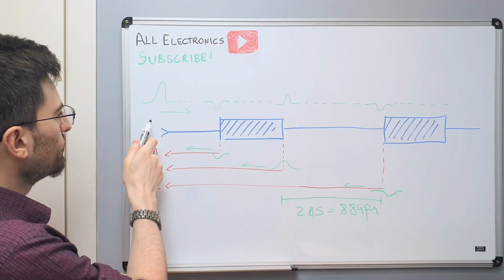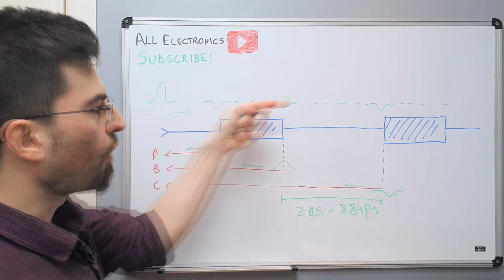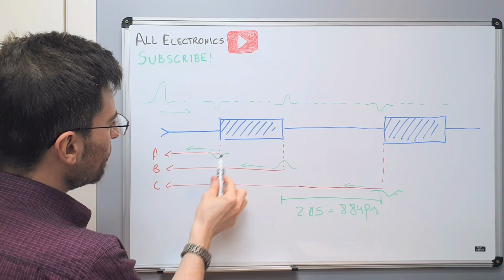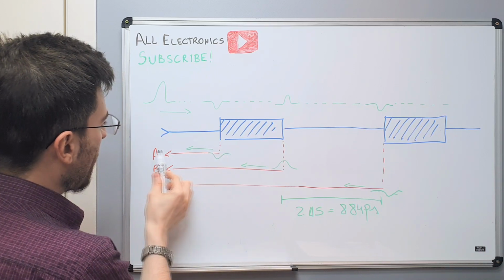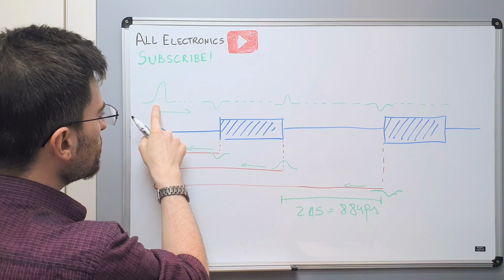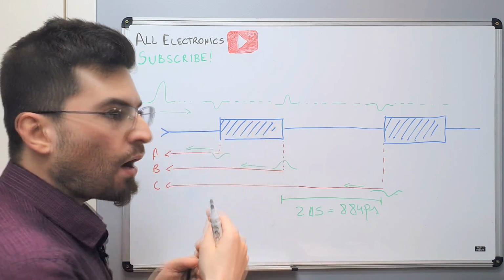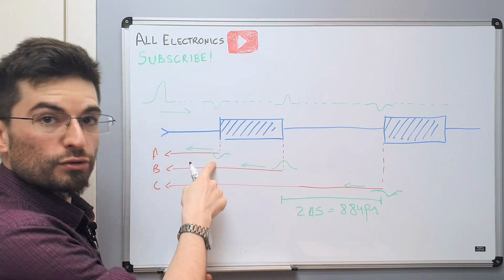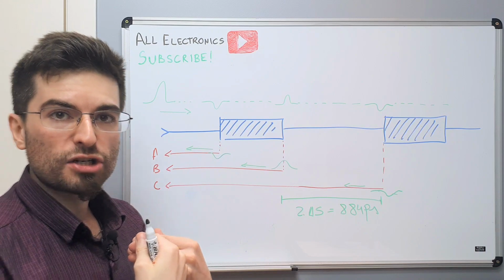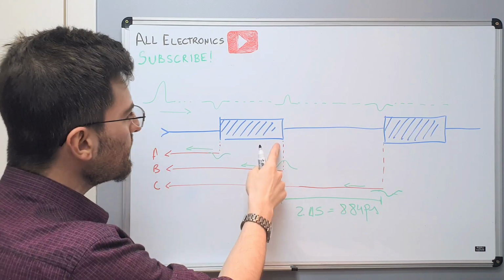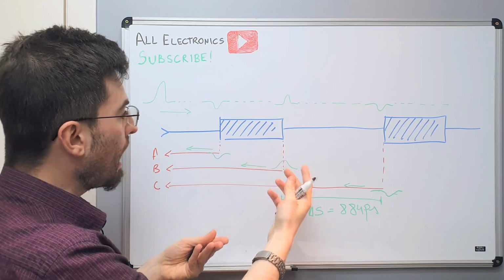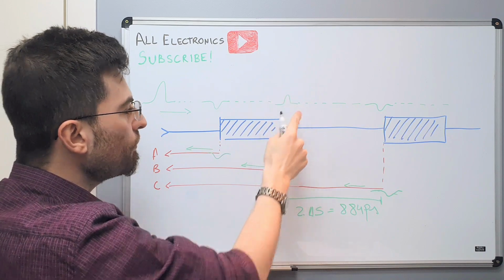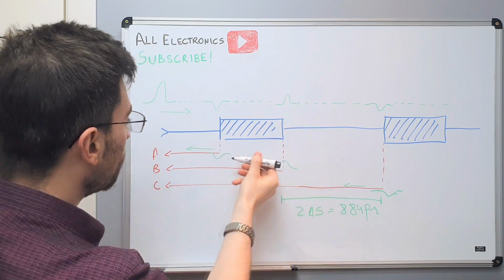We fire the pulse on the port and it starts propagating to the forward direction. When it encounters the first discontinuity, a negative wavefront is reflected back. This is the first reflection that happened. The original pulse keeps propagating, now with a little less energy, because part of the energy was reflected in the first reflection, but the rest of the energy keeps propagating forward and it encounters the second discontinuity. Now from a low impedance to a high impedance, creating a positive wavefront that travels back.